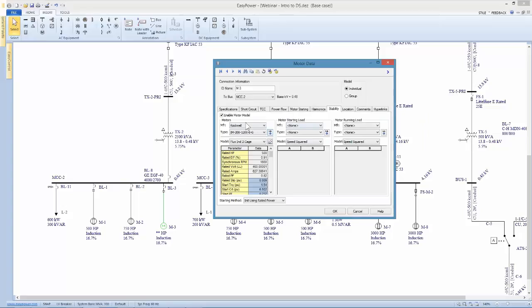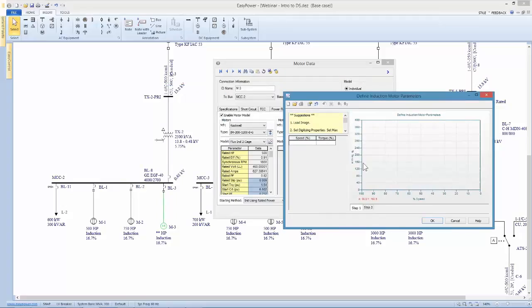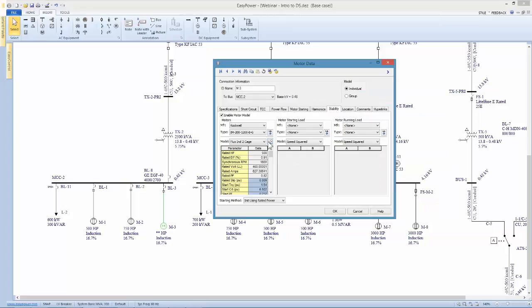And so now as we import that, by default, it gives us this speed squared for both starting and running load. And as that varies from 0 to 1, we'll end up with the same result, but we'll have a squared curve for the performance. Now, if we have a specific data sheet or the torque speed curve, we can actually bring that into the tool and digitize it from whatever the manufacturer's data sheet has given us. And this can be pulled in as a source of data, actually more accurate for our specific application. But in this case, we're going to start with our typical data model.